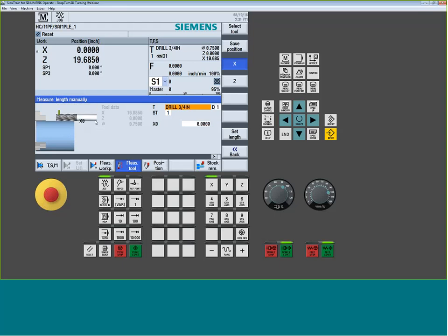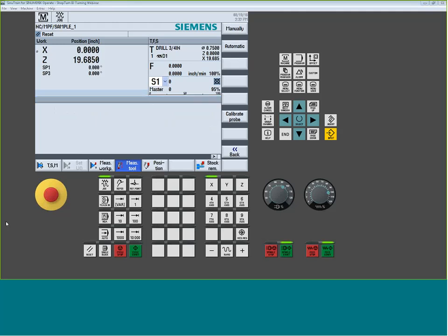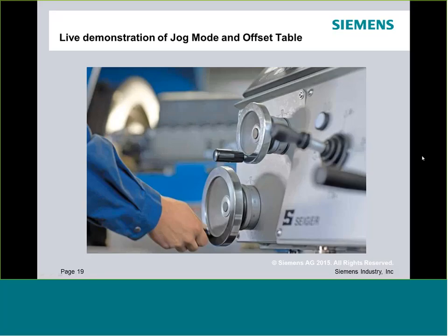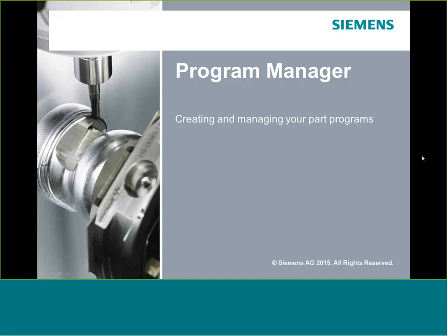A lot of times when I get to live tool machines, guys tend to always have a hard time getting their head around how to set up a live tool machine. So I usually will say, just do it this way first. Once you get it set up and it's cutting accurate parts, then you can go in and play around with sweeping the inside.